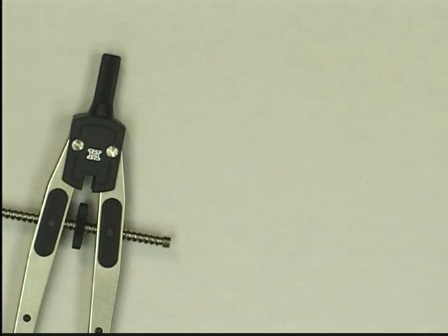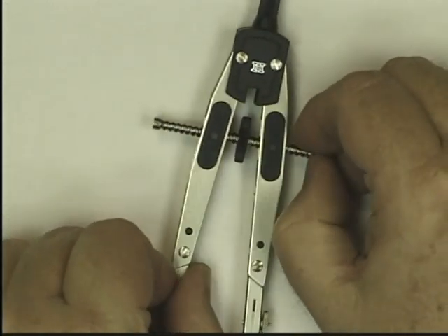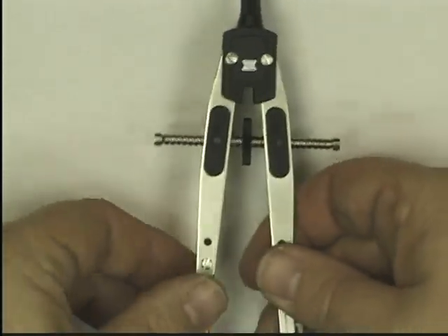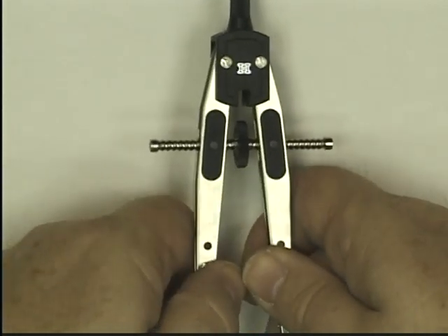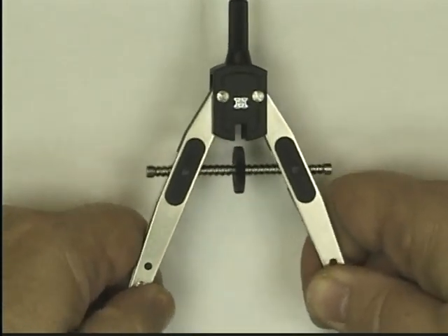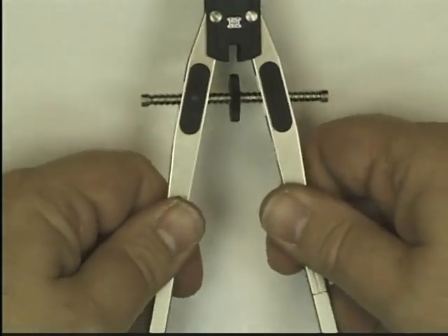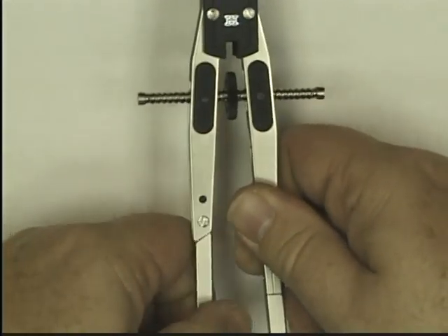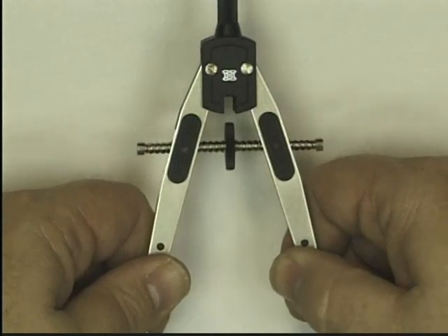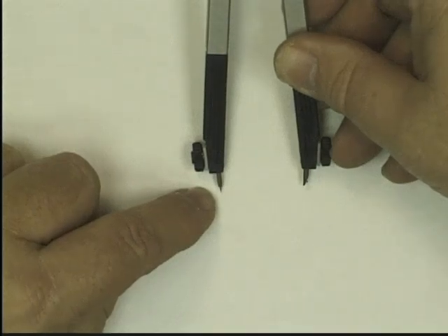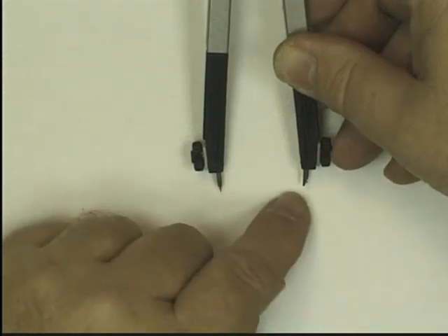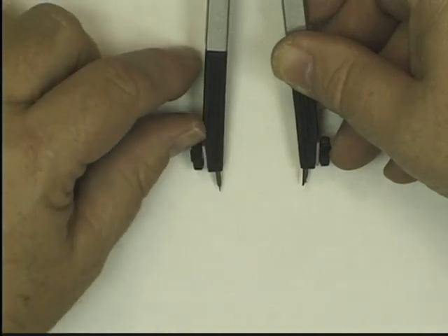Some compasses have a very large smooth thread, and they're called speedboat compasses. You need to find out if you have this before you try this trick. With a speedboat compass, all I have to do is grab this, and very quickly I can speedily move from a small adjustment to a large adjustment. Once I've adjusted the compass to the size that I want, use the point of the compass to mark the center of my arc or circle, and use the lead that's in the compass to scribe the arc or circle.